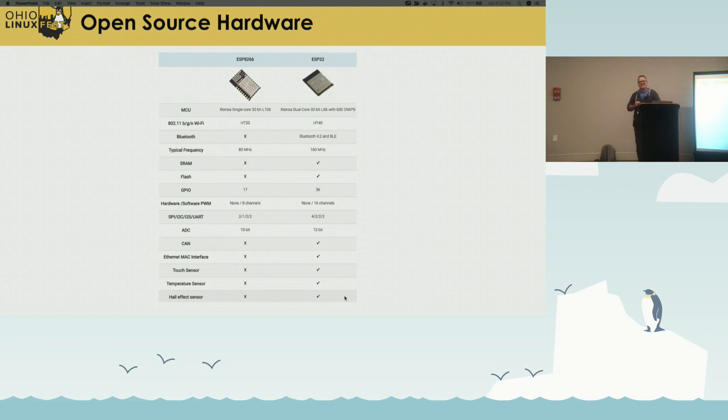It has a temperature sensor. It's not a really good one. It's not consistent from board to board. And also, this can on the outside, which doubles as a heat sink, kind of prevents you from making contact with it. So I don't know why they put it on there. It was dumb, but it works.